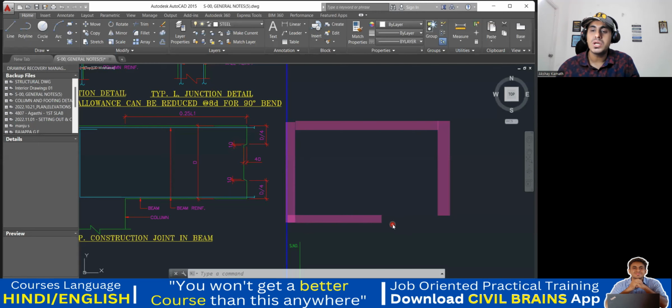Now, when you leave the concreting, what happened? You came back after 2 hours. So as a result of that, a kind of joint is created. So that is called a construction joint. Got it as the first thing. Now what happened? You cannot start your concreting directly from here. So whenever you're leaving a construction joint in the beam, you need to understand the concept of the bending moment. Wherever your bending moment is minimum, or at the point of contraflexion, you have to stop your concreting. For example, if I take a simple beam, where shall I take?